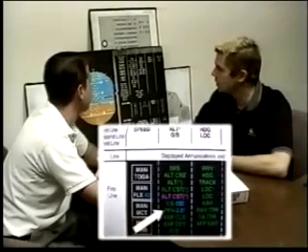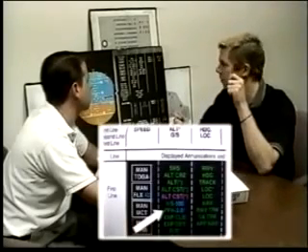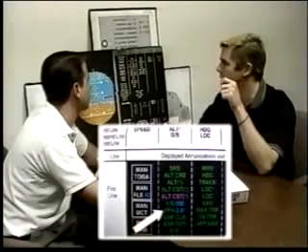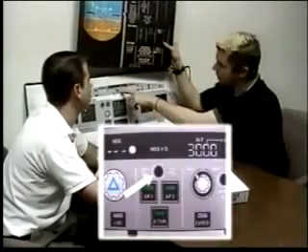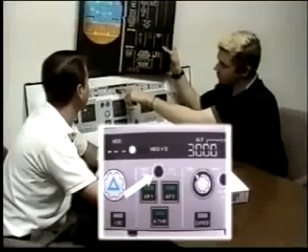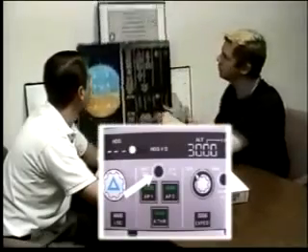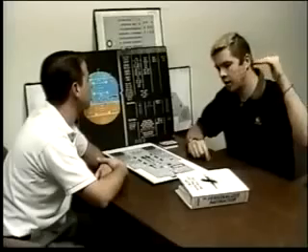FPA is similar. It's referencing a constant descent or climb, but instead of referencing a feet per minute, it's referencing a glide path. The only way we can get that is by being in the track flight path angle mode down here, and this currently indicates heading vertical speed. But if we had track flight path angle, we could say, I want to descend 3 degrees.